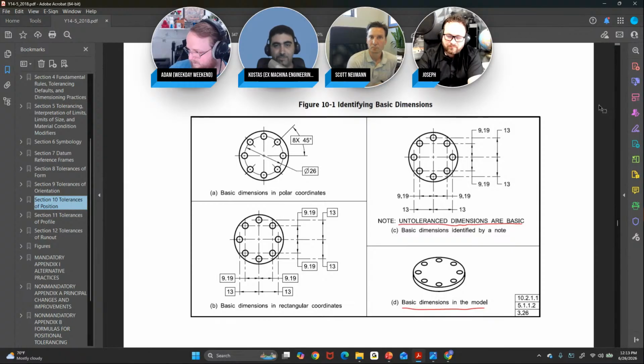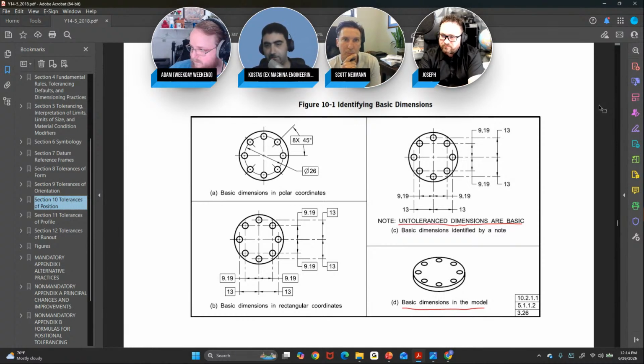And can I just say for our Libre users that if you make a single hole and then do a circular pattern of it, you will get the bolt circle showing in your drawing automatically. That's just a CAD use thing, if you're so inclined. Whereas if you pop in the individual holes, you can still draw the bolt circle, but you won't get it automatically.